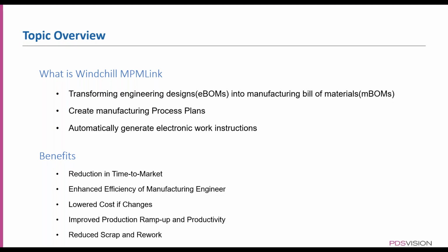And then we'll also create the process plans, basically how we would go in and assemble a product. So in a factory or shop floor, how you go in and manufacture this product, what stages are involved, and how you basically set the stages and assign resources to different stages. That's something you can do in the system, and eventually generate a work instruction out of this. So once I've put in my process plan and I've assigned resources to it, whatever is needed at every station, I can go in and export out the work instructions in a PDF format out of that process plan as well.